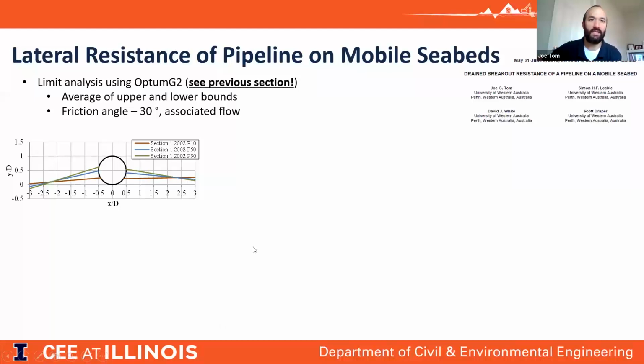This is a case in 2002, which is basically right after pipe lay. If you focus on the blue line there where my mouse is, that is the P50, or the median profile, for that particular, I think, 200-meter long section of pipeline. So you have about 40% embedment, but then you have a gentle downward sloping seabed going away. So you have a bit of deposition there.